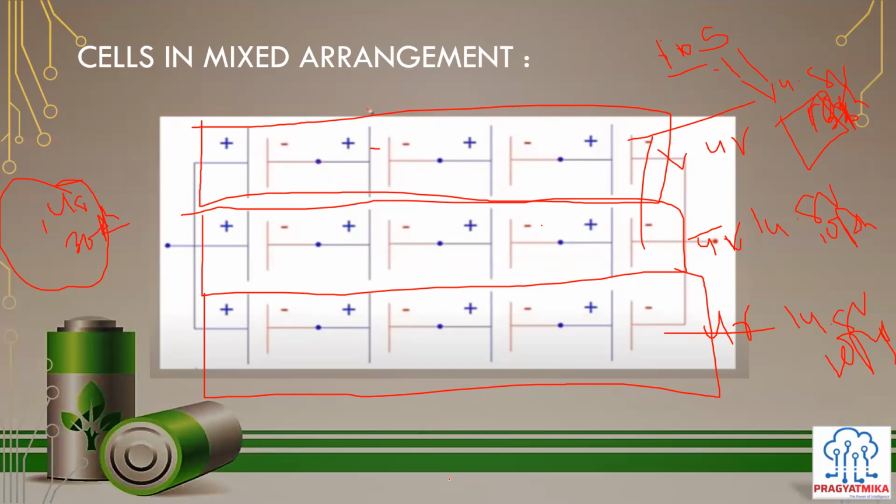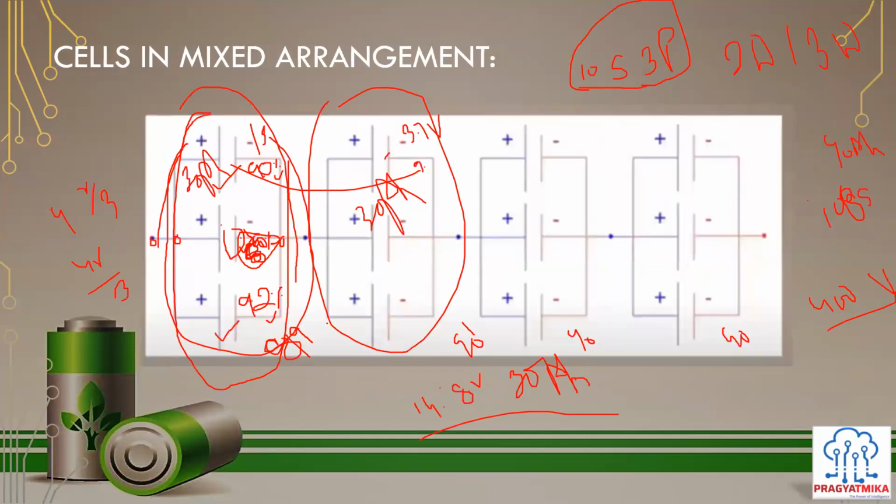And so any online monitoring method, like any IoT based monitoring method for your battery pack, would be working at the individual cell level. So there, this series oriented mixed arrangement would be working. You can't work on the parallel arrangement. If it is a parallel arrangement, whatever IoT based method you apply, the error will always remain in the design, that it will give you the nature of all the modules together. It will not be able to tell you about an individual cell.